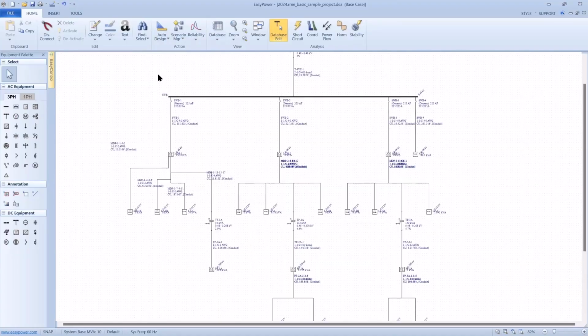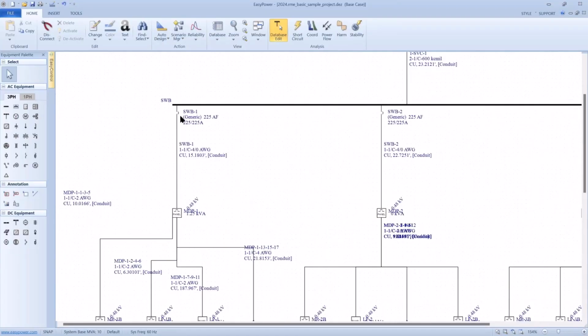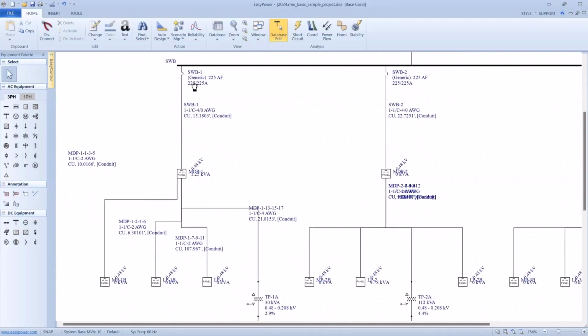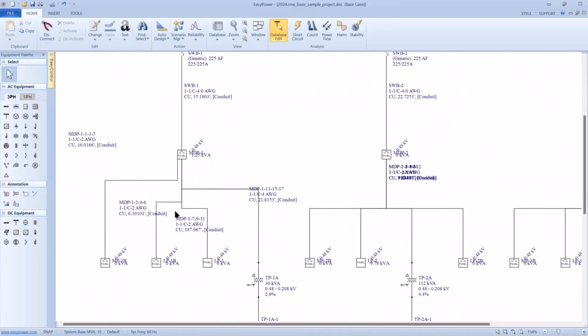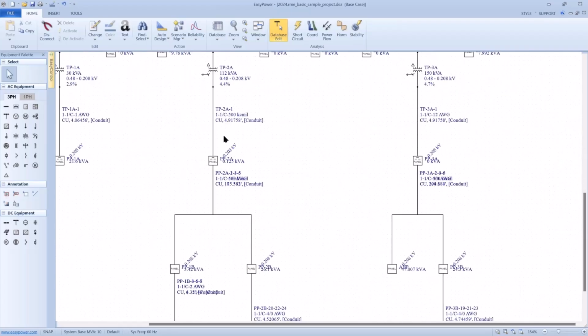Color comes back to me. Now you can see that the values are a little bit different because I have a different decision lookup table, but now I have generic part numbers. My cables that I moved around stayed, and my cable sizing looks like it's pretty much consistent with what we saw before. Likewise on transformer sizing, which I would expect.